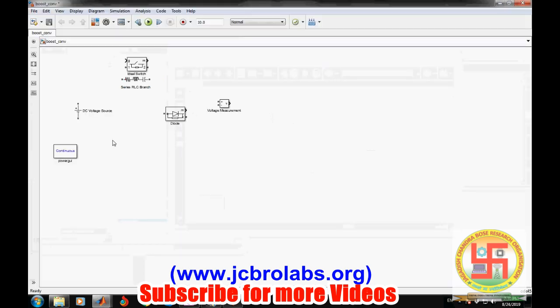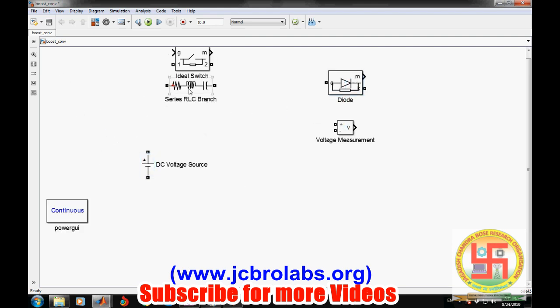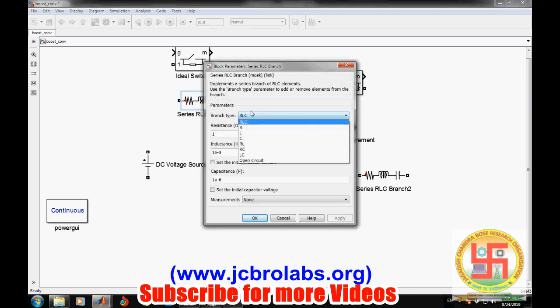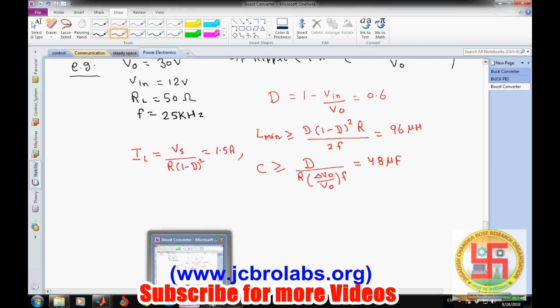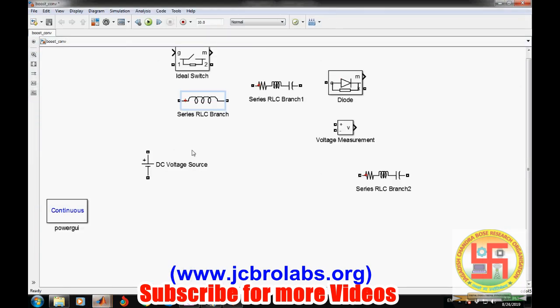So now let's make it. Let's zoom a little bit. First of all we need three such branches for R, L and C. First we'll convert it into an L, so only L is there, and the value of this inductor is 96 microhenry. So let's set the unit to micro, 10⁻⁶, and here it should be 96. That's done.